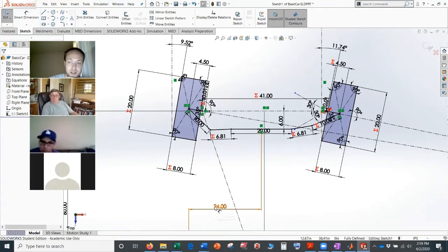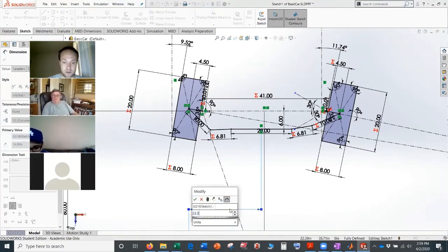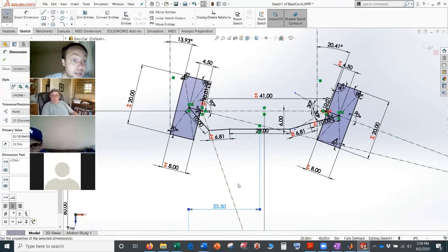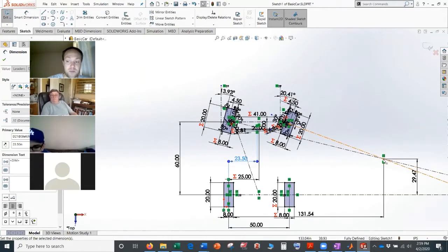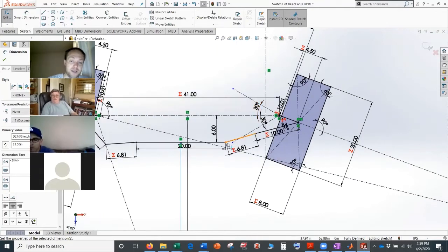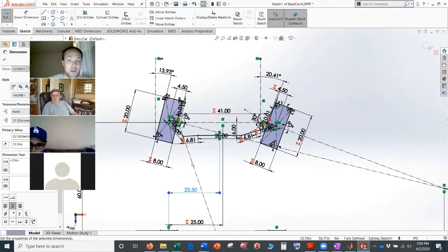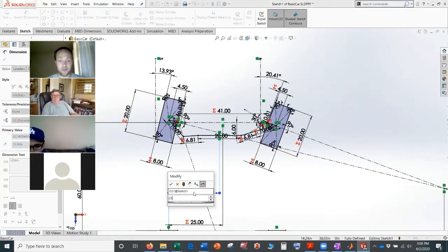And what you'll start to see is, let's go to 23.5. And you see what I begin to get limited by, right? My turning radius depends a lot on how much I can turn my two tires. Right now I'm at 131 inches on this turning radius for this turn, but what's starting to happen is you can see as the rack moves to the left, the tie rod right here and the steering arm begin to go over center. So that's what we call over center. You should have a stop so that these do not go in a straight line, because imagine now when you try and go left, it just gets stuck. Right now we didn't hit here. We just got stuck right here. So this is probably the best we can do with this setup. Go back to 25, right?